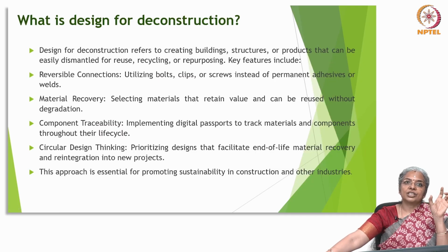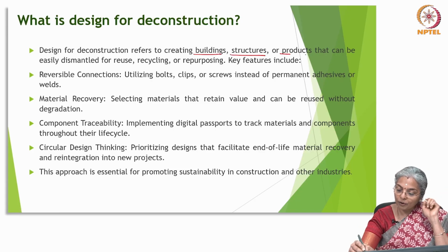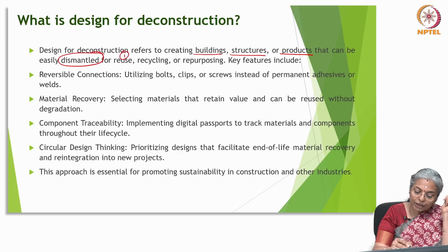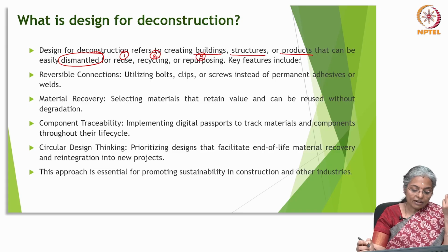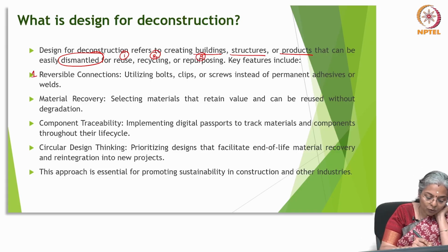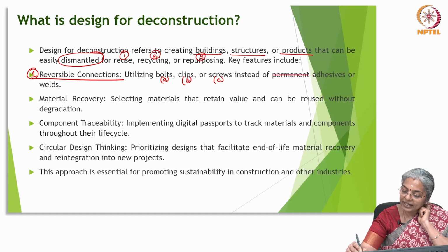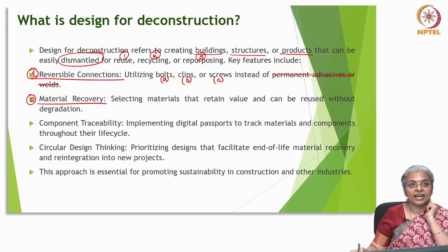Design for deconstruction refers to creating buildings, structures or products that can be dismantled easily for reuse, recycling or repurposing. Their features include, first and foremost, reversible connections. So, you can use bolts, clips, screws instead of permanent adhesives or welds. Then second, you should be able to conduct material recovery.